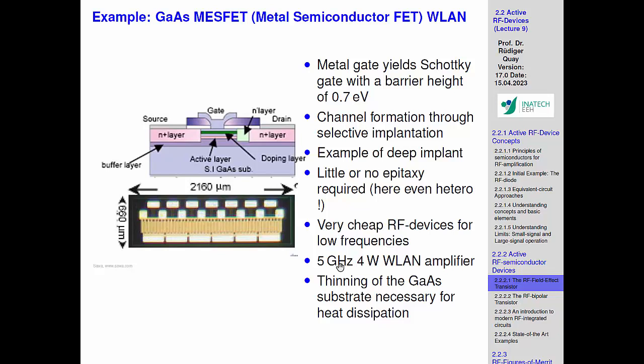And you're seeing here that the transistors which we make then, they're relatively big. The gate structures are small, but the overall area is quite significant. So for the microwave devices, you can see them. Yeah, so this is 2 by nearly 1 millimeter.